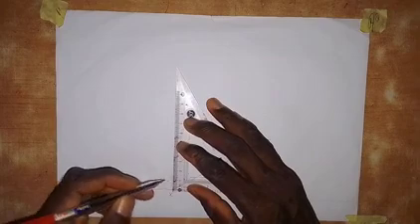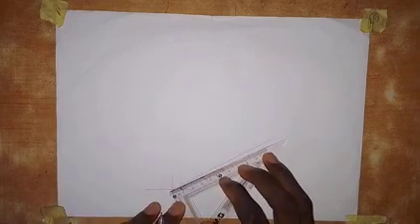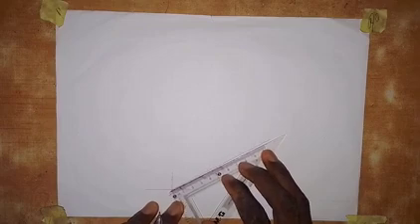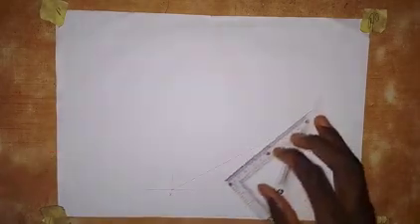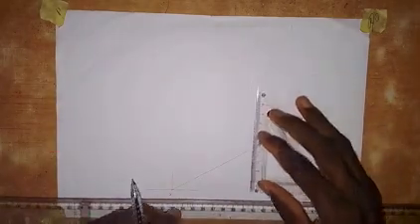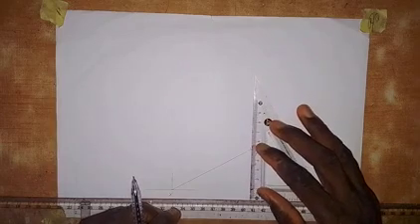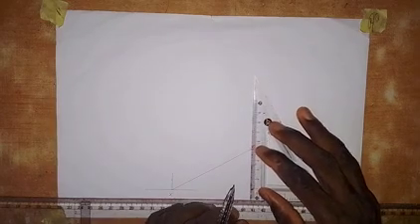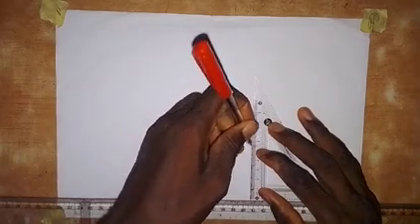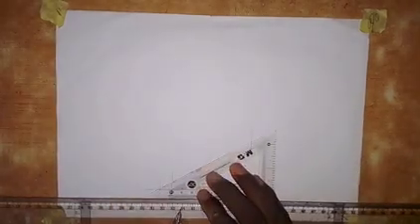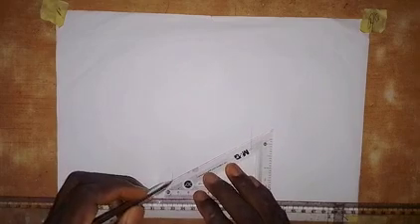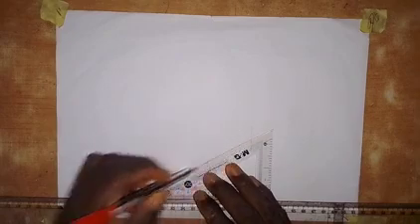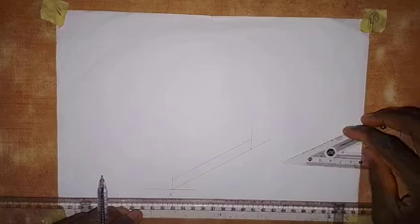Okay, then I will take a measurement of 10 millimeters here as thickness on the front elevation. So this is 10 millimeters. Then along this side here, I will take 90 millimeters, which is the length of the rectangle. So this is 90. So coming to this point here, I will draw a short vertical line like this. Okay, then I will transfer this 10 onto that. So we have this. So this is the rectangle that we see in the front elevation.